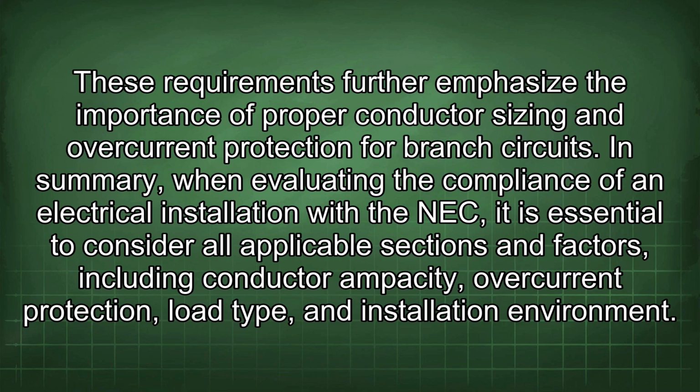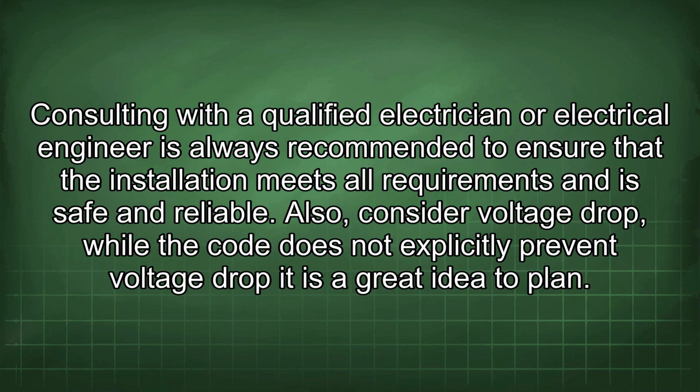In summary, when evaluating the compliance of an electrical installation with NEC, it is essential to consider all applicable sections and factors, including conductor ampacity, overcurrent protection, load type, and installation environment. Consulting with a qualified electrician or electrical engineer is always recommended to ensure that the installation meets all requirements and is safe and reliable. Also, consider voltage drop.